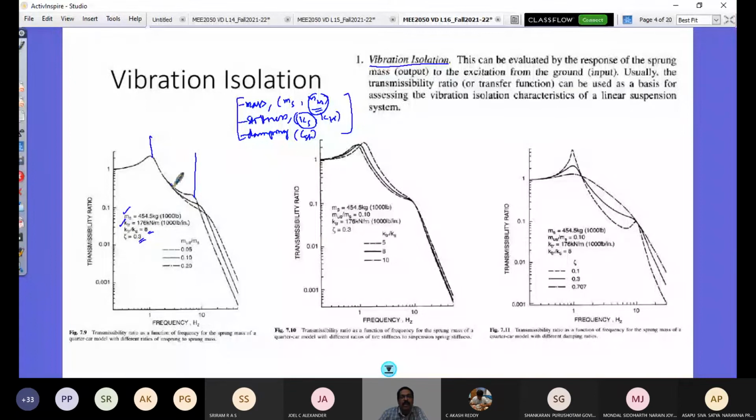However, beyond the midpoint of the mid frequency range, you see that this line is referring to a low mass. So that means instead of a steel wheel, if I have an alloy wheel, that is going to give me good transmissibility, a minimum value of transmissibility. So the main objective is to minimize these functions on the y-axis. So I have the minimum value here.